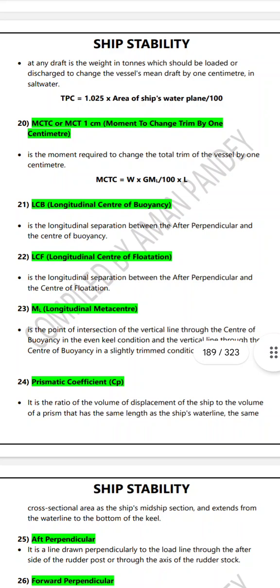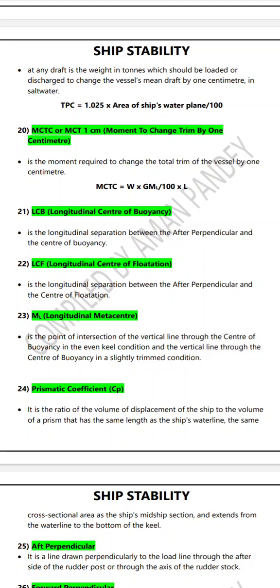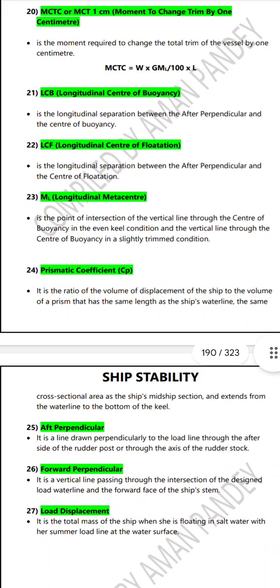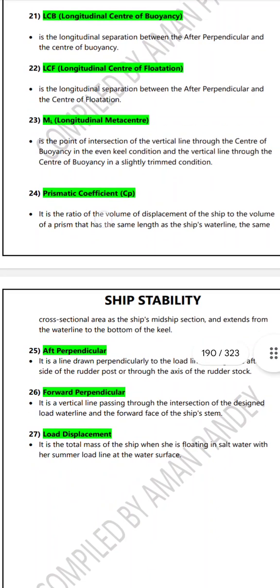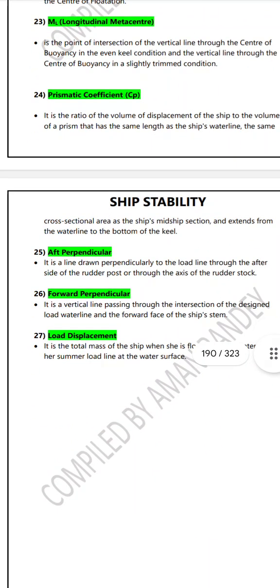Moment to change trim is the moment required to change the total trim of the vessel by 1 centimeter. LCB is the longitudinal distance between the perpendicular and the center of buoyancy. LCF is the longitudinal distance between the perpendicular and the center of flotation. Then longitudinal metacenter.